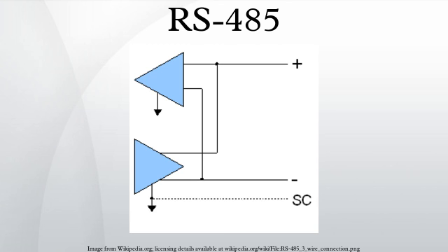In addition to the A and B connections, the EIA standard also specifies a third interconnection point called C, which is the common signal reference ground. These names are all in use on various equipment, but the actual standard released by EIA only uses the names A and B. However, despite the unambiguous standard, there is much confusion about which is which. The RS-485 signaling specification states that signal A is the inverting or minus pin and signal B is the non-inverting or plus pin. This is in conflict with the AB naming used by a number of differential transceiver manufacturers, including, among others, Texas Instruments,